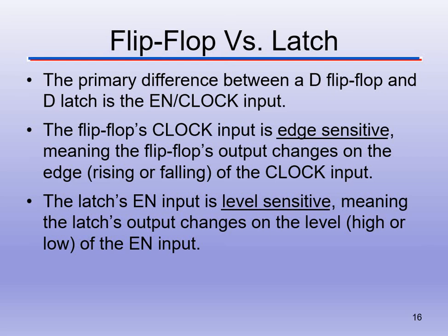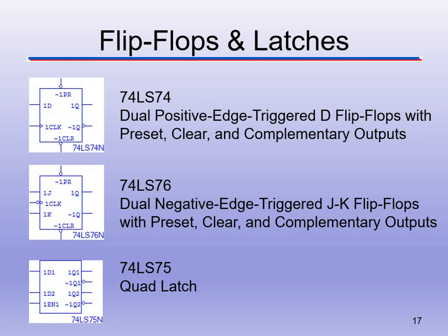With the latch, it's level sensitive. So if enable is 0 or enable is 1, those are going to be the two different meanings. So that's really the difference between latch and flip-flop. With the flip-flop, we have a clock that's going to automatically toggle through the signals. With the latch, we have enable, so you manually tell it when to turn on, when to turn off, and follow the signal. That's really the difference between the two.